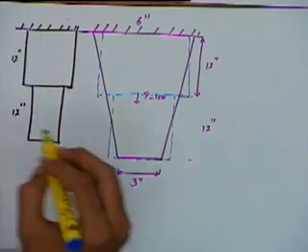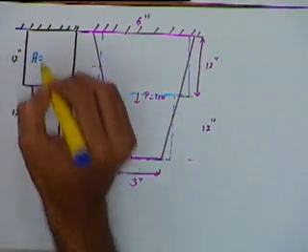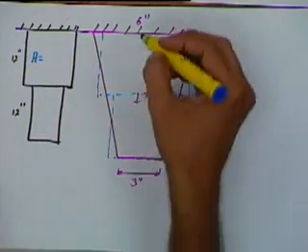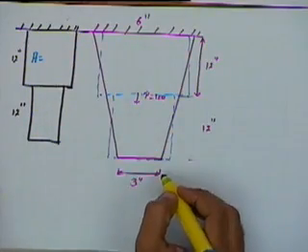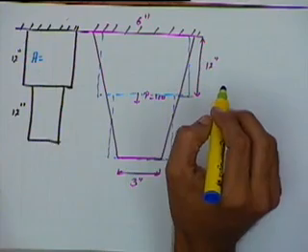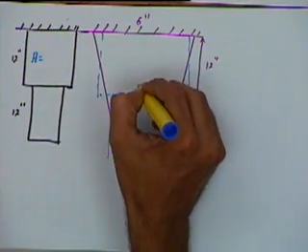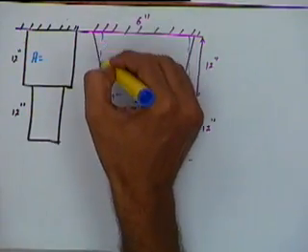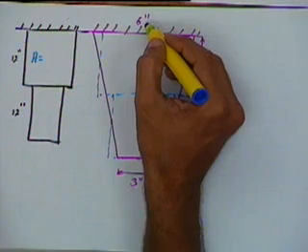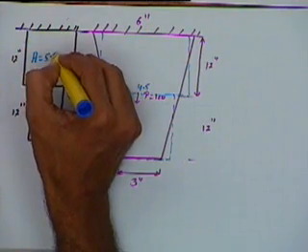Okay, let's say for this element my area of cross section A is 3 at one end and 6 at the other end, and I have taken a linear variation. So at the center, how much will I get? 4.5. So for this element I will get between 4.5 and 6. If I take an average, I will get the area of cross section to be 5.25.